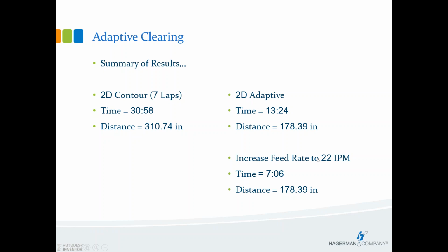If you can speed it up, which you can, by the way, you can cut your time down dramatically, even down to a fourth. With that being said, again, just something to consider. I'm not trying to sway you guys one way or another. I just want you to know that HSM offers both types of machining. I would say if your shape allows, use the adaptive, you will come out ahead. And this is just rawly comparing your feeds and speeds.